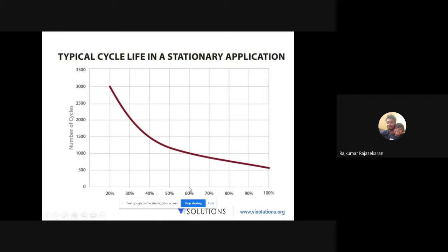You can see that every time we take a look at batteries' capacity, they will say that it's going to hold this much amount of ampere hour, but the terms and conditions will be until some number of cycles, let's say 500 or 1000 cycles, where cycles mean charging and discharging cycles. They would have clearly mentioned it in the data sheet. Maybe not on the battery itself, but it will be clearly mentioned in the data sheet for the model. So it can hold only up till that, but after that its characteristics may change. Most of the time it does change. That's the truth.